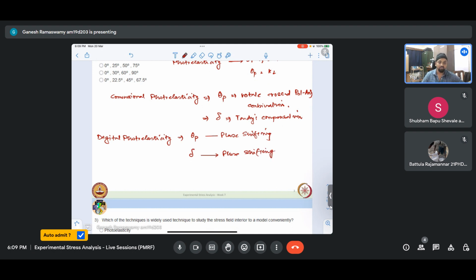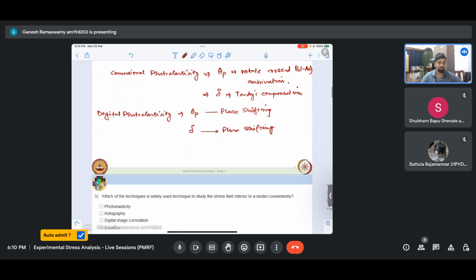Basically, we take 4 images with our plane polariscope arrangement with different configurations to obtain theta p. Then that is followed by 6 more images of circular polariscope with some specific orientations, carefully chosen to minimize quarter wave plate error and keep the quarter wave plates crossed. Once we do the same intensity subtraction and addition, we will be able to discern the isochromatics at each and every point, which is nothing but discerning n, so delta by 2 pi.